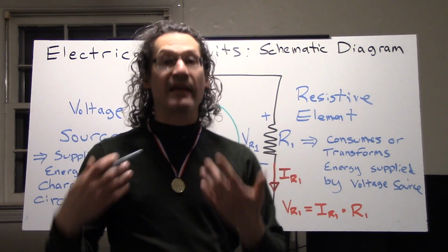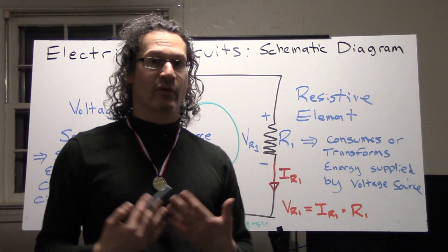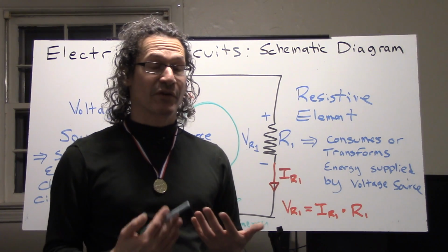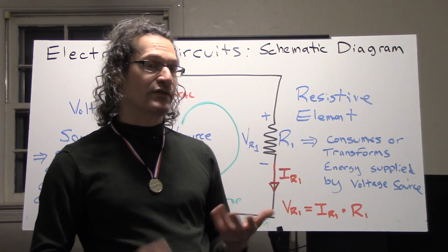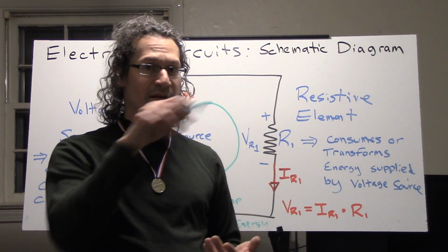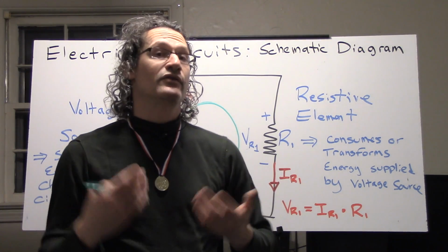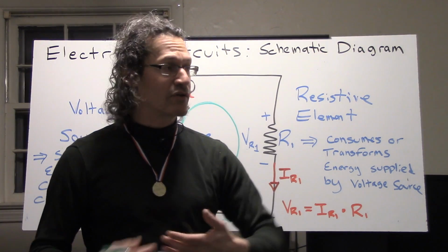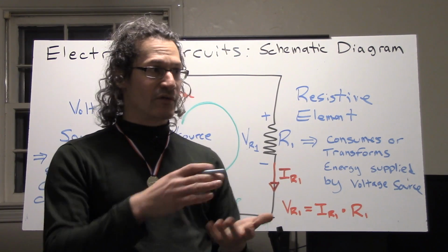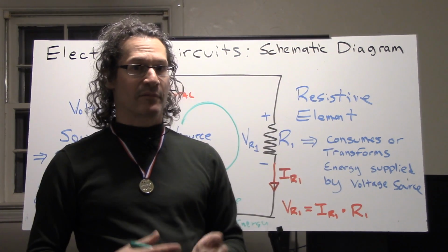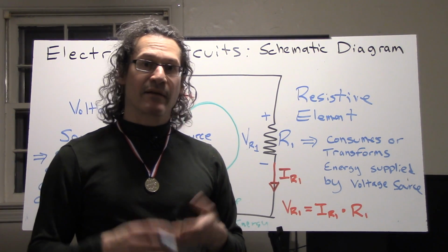This is consistent for any loop that we can take. So when we look at a series circuit, a parallel circuit, or a series-parallel combination circuit, this law applies. And it's going to help us analyze the circuit when we see that there's this conservation. What we'll see more so in the parallel circuit, though, is that current is also conserved. The conservation of charge through any junction is equal. You can think of water flowing into a junction. Whatever goes in comes out, but it may get split up into different parts before recombining.